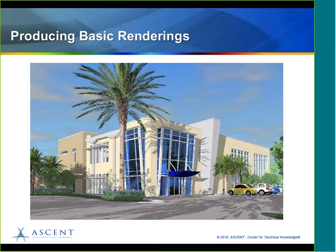So the things to remember, though, when you are producing basic renderings is that, of course, you need to pick the 3D view. You can see this particular one is a perspective. You want to make sure that your materials are applied to the model elements. And I think you can probably see here, this looks like kind of a corrugated metal roof. Here we've got something bright blue on the sunscreen, the shade over the front door. So you're using your particular materials. You want to turn on shadows because that's going to give you some help as you're producing your rendering.